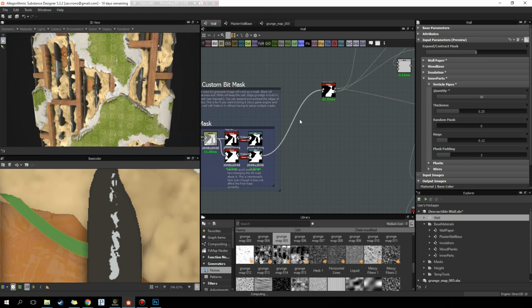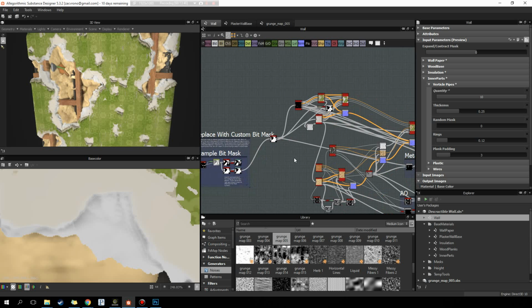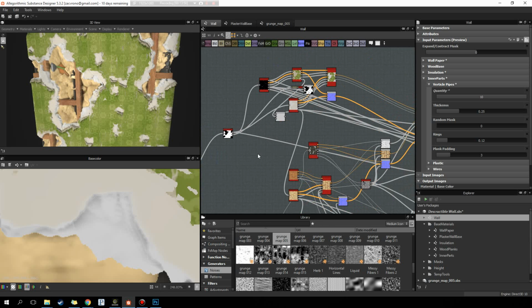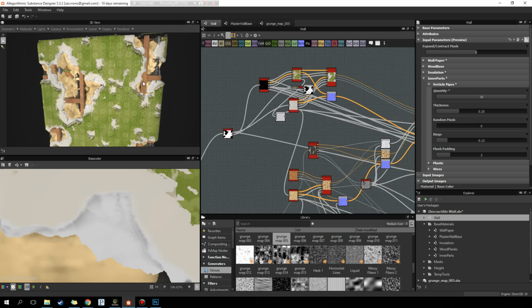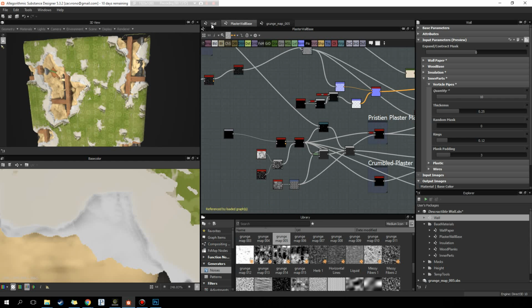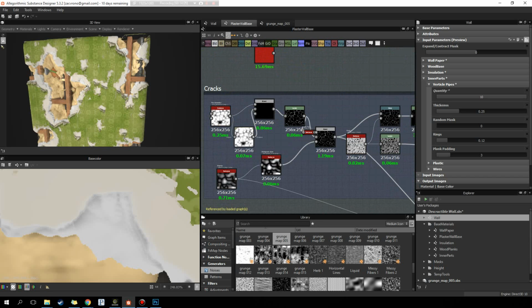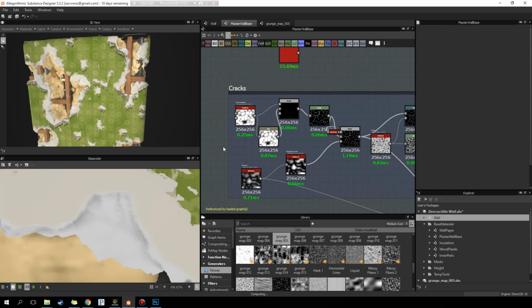default. I was able to do this by, they have a wiki on it, on the efficiency. You can find on their site somewhere. I think you can just Google it. And it's like increasing the processing time of Substance Designer or something. I'll post a link below in the description. The main thing I learned though is slopes, blurs, and warps. Warp nodes hurt performance, so if you're going to use them, try and keep the sample size as low as possible. And the second part is you want to keep your resolutions as low as possible as well.